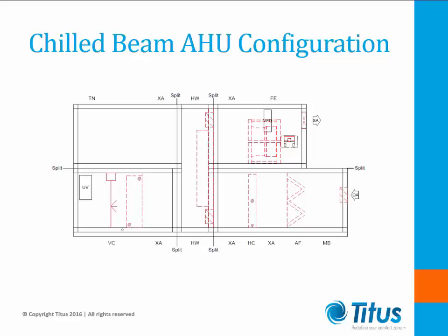The primary airflow is based on a required supply airflow for chilled beam induction to meet latent capacity and outside air for ventilation. In most cases, supply air for latent capacity is the greatest of the three. During peak cooling hours, outside air generally has the highest enthalpy and thus requires the most energy to cool and dehumidify. For this reason, buildings with high humidity loads should mix return air with outside air to provide additional latent capacity in minimizing energy consumption.